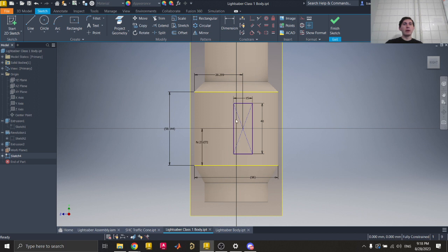So now, how would we go doing a similar process? How would we go about centering it horizontally? Use that measurement for 66. So I have this, and then I'll select that, divided by 2, check mark, bam, we are centered. And then you can see everything here. Now if I try to drag and move any of these lines, none of them want to move, which means everything is properly constrained just as we need it to be.